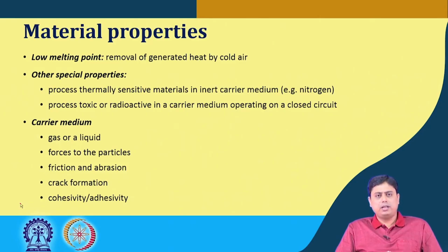Other properties that are sometimes important: if the process is thermally sensitive for the materials, then the grinding operation can be carried out in presence of an inert atmosphere or inert carrier medium, because the material itself is temperature sensitive. So, in presence of atmospheric air or oxygen, it can create some hazard.